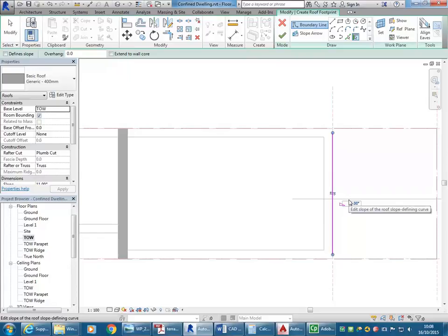And then change that angle. So the angle will come up, it'll be 30, and just change that to 11. So just go to the green tab, and then just go pick walls. So in the draw panel, the last button, where you've got all the shapes. The very right, so the end of the building. And then you can change the angle. So you're going to click on where it's 30 and change that to 11.